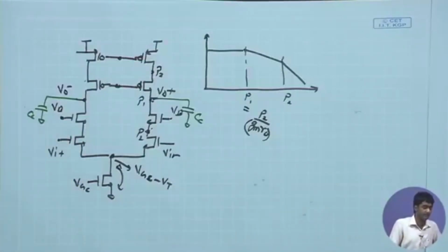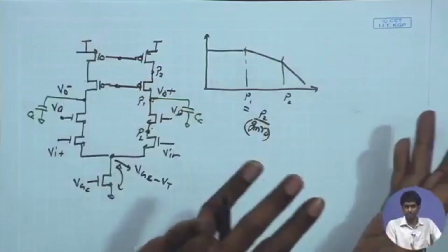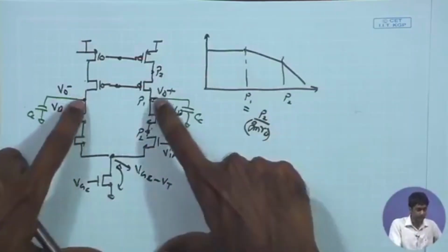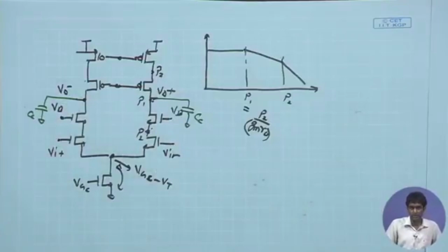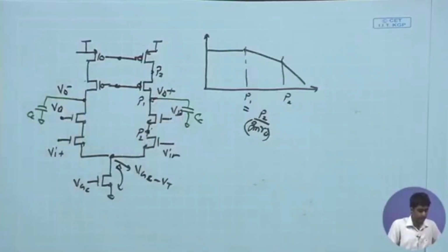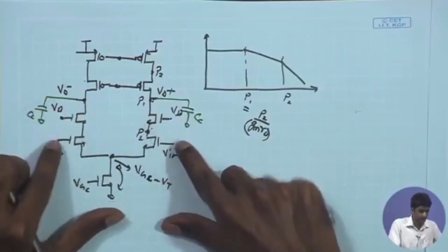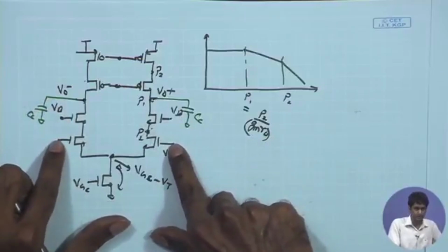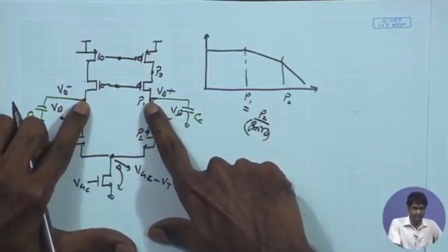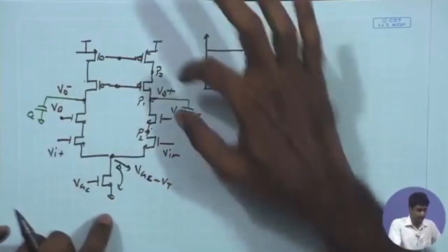In our example, we have stated that the output DC common mode is determined by common mode feedback if it is a fully differential operation, and with the help of that we are fixing the input common mode level. If we do that here, we will be pushing the input common mode DC level or input bias point close to the output DC level.